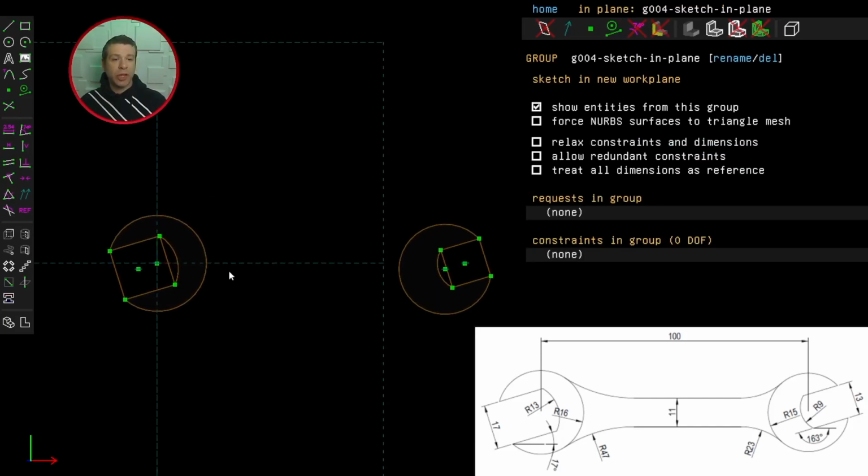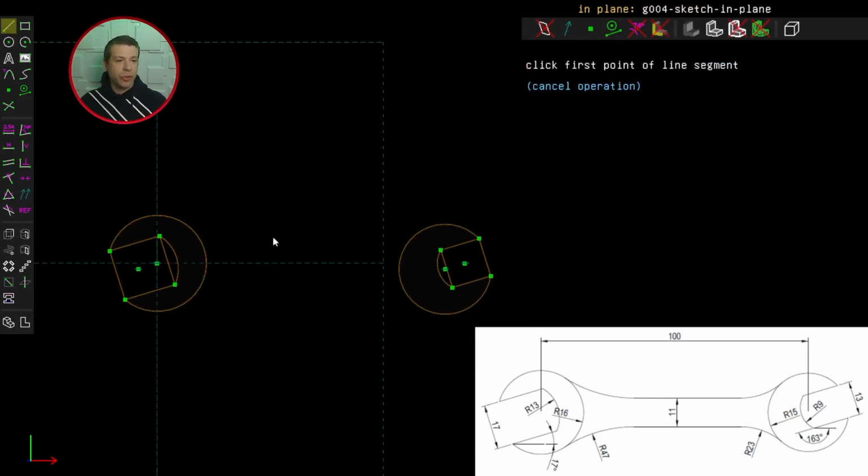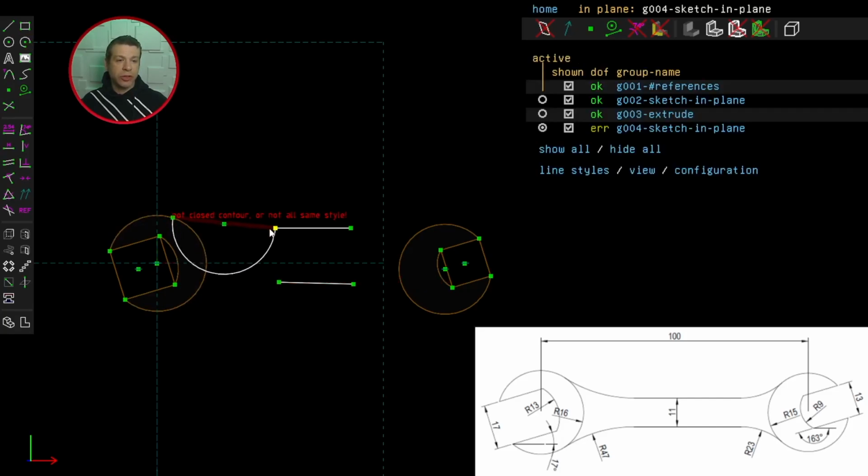That's now our new work plane, and I'm going to sketch the bridge now. I'll start with 2 segment lines, and I'll join these line segments with an arc by selecting the arc tool and highlighting one of the semicircles first and clicking on the dots there. And to make sure that they're overlaid, you'll find that they're highlighted yellow when you put your mouse over them. For now, I'm just going to eyeball the sketch, but we will constrain it later.